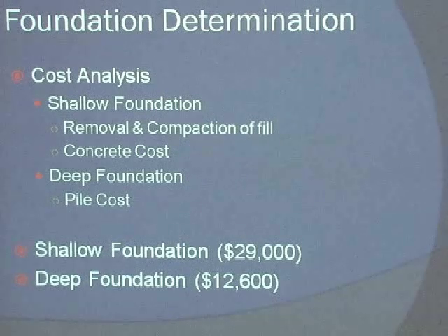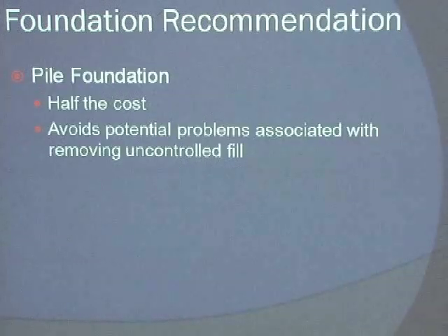As you can see, the shallow foundation is considerably more expensive, and thus our recommendation is to use pile foundation for both the retail and the restaurant structures for 2 reasons. 1, obviously economics, and 2, it will avoid any potential issues associated with the removal of uncontrolled fill. Now to discuss the environmental aspect, here's Joseph.